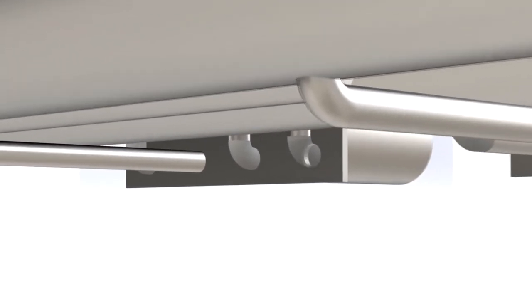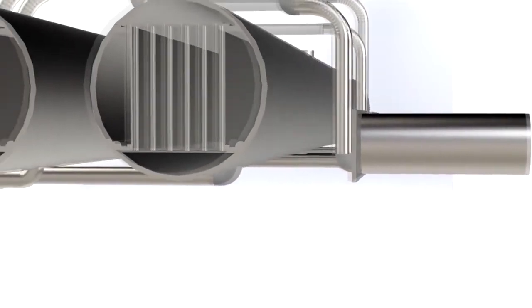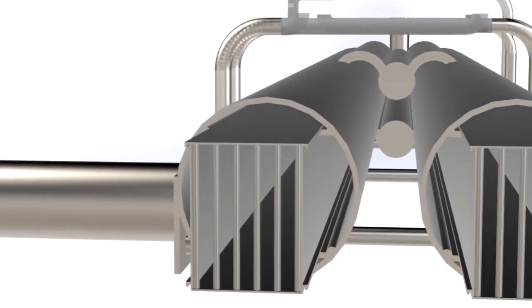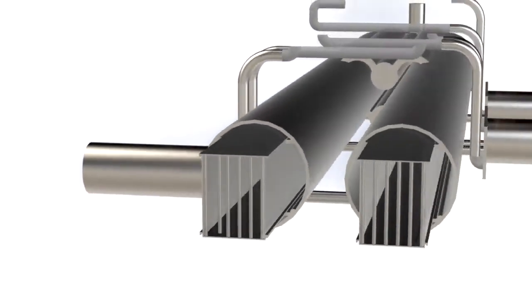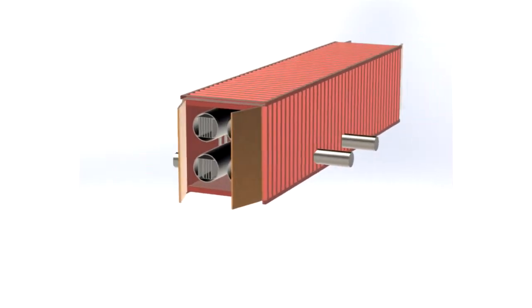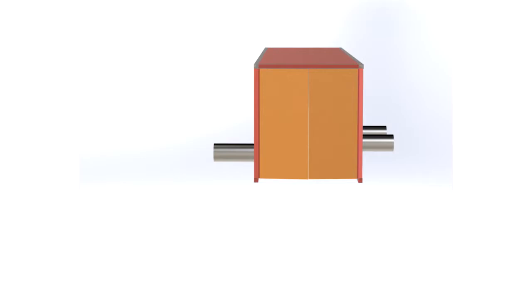Meanwhile, the salt water gets concentrated further and further as we go through the different effects, and it is collected at the right side. An advantage of the system is that the heat exchanger slides out and the tubes are replaceable. So once there is a lot of gunk, we can just easily replace the tubes, and it is very easy to do. So that is how a latent heat exchanger in this system works.